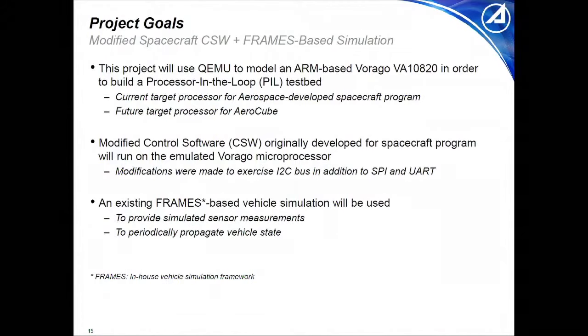It wasn't surgery to overcome the limitations of running on a SIL or to rehost the flight software. Basically, all of our communication was over SPI. We decided to take one of the functionalities of the software and put that on an I2C bus instead, simply so that we could build out the I2C peripheral in the system on a chip in QEMU and exercise that peripheral.